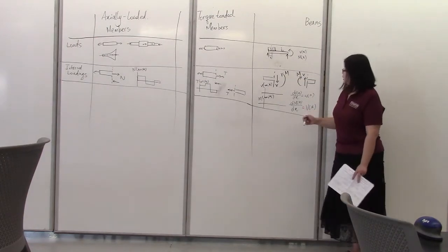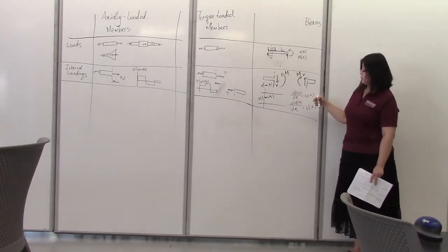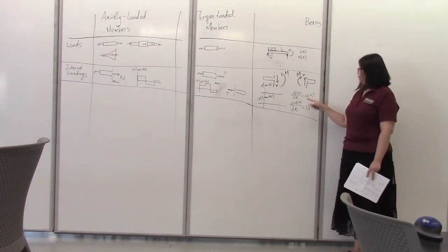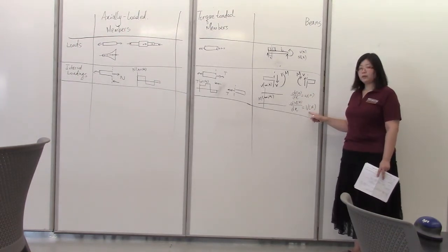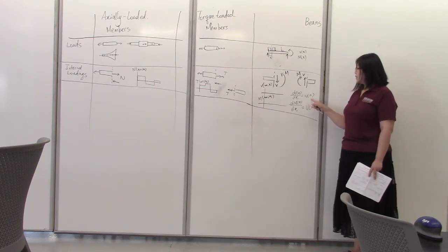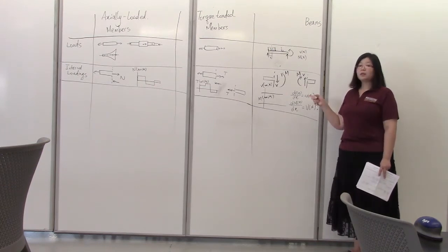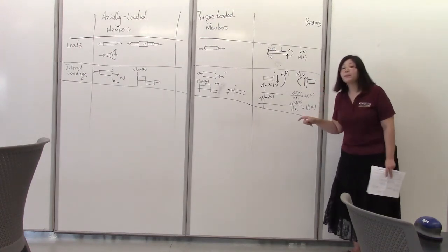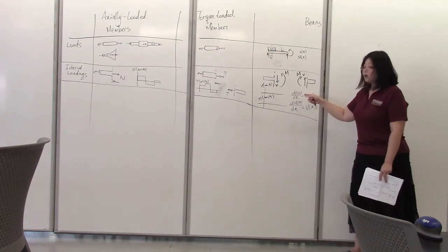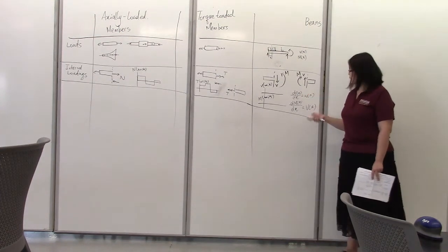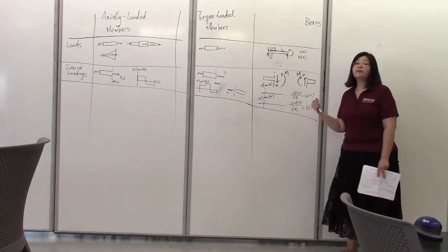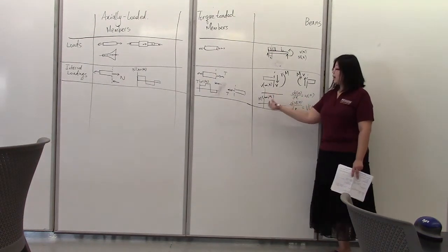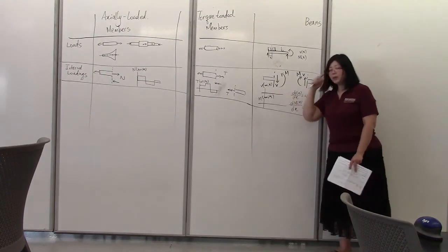Okay. So these two relationships tell us how V and M should vary when you look at the load and the shear force. For example, this distributed load gives the slope of V, and V gives the slope of M, and therefore V is always one order higher than W, and M is always one order higher than V. So based on that, you could sketch V and M for different segments on the beam.